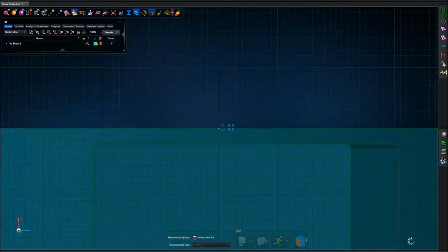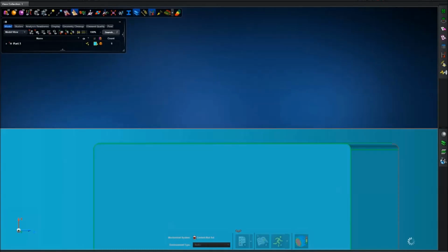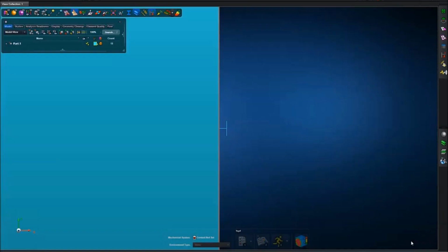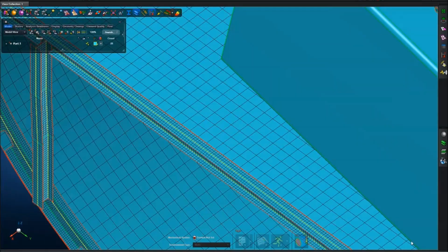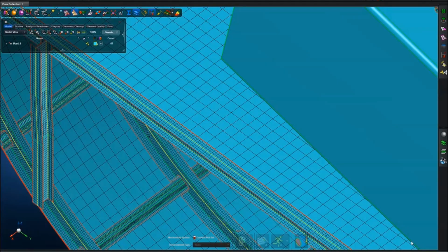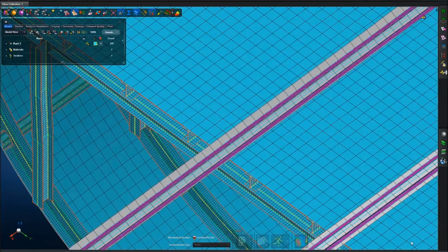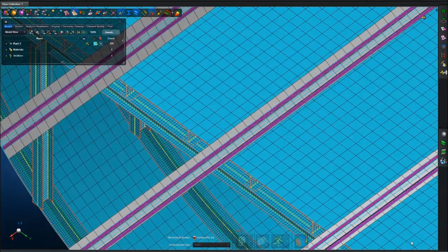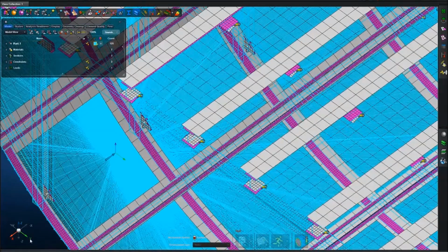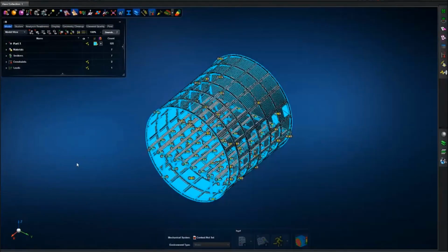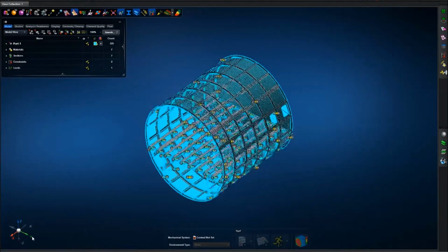Then the Panda FEM script kicks in for the detailed FEM definition, and this effectively rebuilds the GFEM based on detailed panel and stringer definition. You can see here we've got a top hat definition for this particular part of the fuselage that's glued into the structure, and can be run, analysed, post-processed, and then tied back into the global FEM of the fuselage definition. So there are some potentially massive time savings here in terms of the overall process.